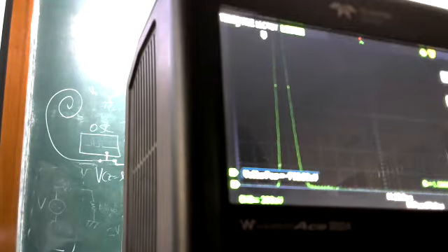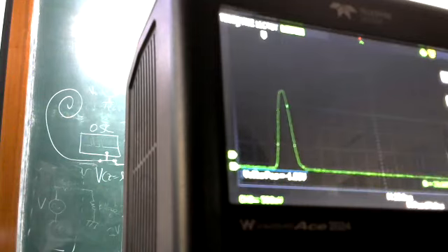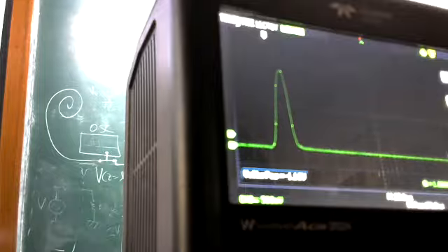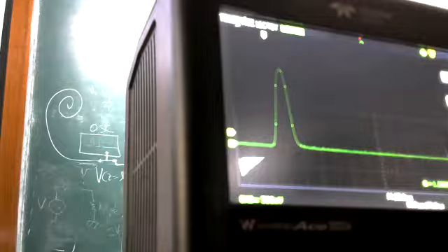Yeah, the screen doesn't fit that. Okay, we go back to the previous one. 500 millivolts per division, 4 boxes, 2 volts, 0 to 2 volts. This is with a 1 mega ohm input impedance. So it's measuring the true V0.